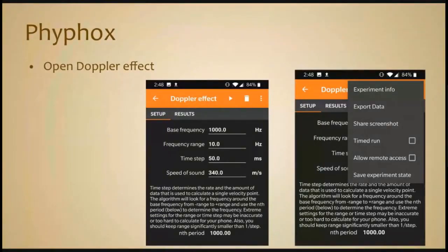And we produce a sinusoid at 1000 hertz. And then, after we record the sound wave of 1002 hertz, we multiply that particular sinusoid by our own generated sinusoid, which is oscillating at 1000 hertz.